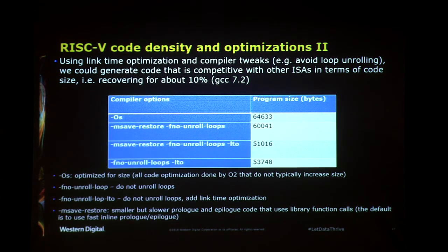There's a one-page section in the spec, read it, it's very interesting, which explains why there shall not be an instruction that handles your prologue and epilogue code, like multi-load and multi-save instructions that can save or load 32 registers with one instruction. The explanation is that there's no point in doing that, because if you do it with a function, you'll get the same speed, which may or may not be true. There are tricks for how to take advantage of such an instruction. So that's a little bit of an uphill battle, but okay.